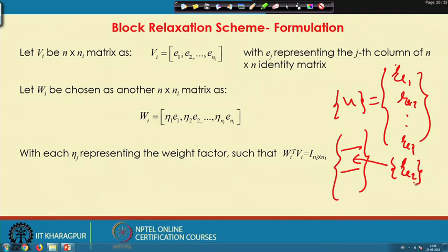So, I have to multiply something with x_i2 to make it assemblable to the U matrix, which comes from these terms, eta_1 e_1, eta_2 e_2. If there is no overlap, then x_i2 into e_2 will keep x_i2 here. If there is overlap, then maybe this is the location of x_i1, and from here we will start the location of x_i2. So, I have to multiply something with e_1.